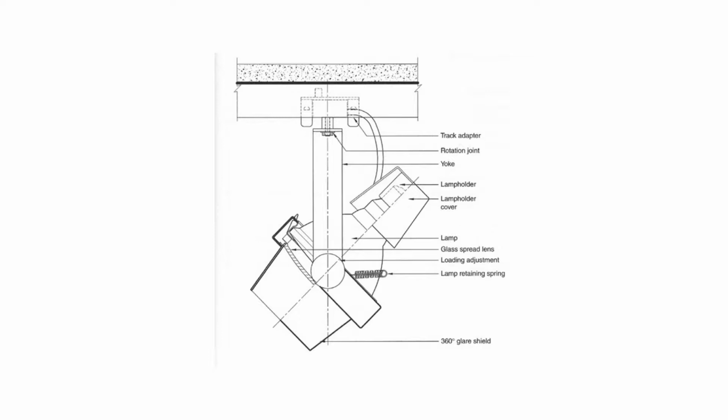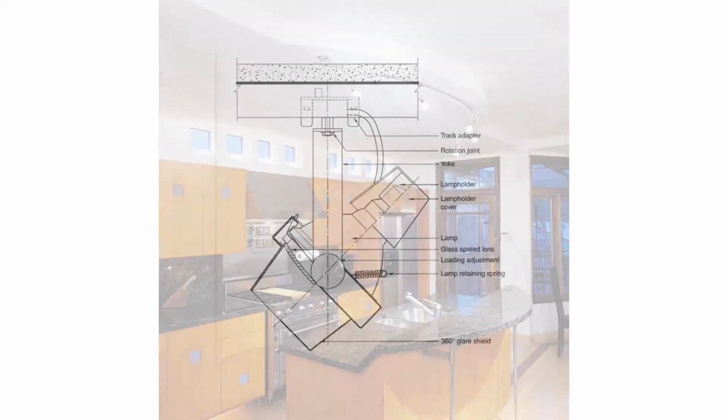It's called a gimbal fixture because it has a gimbal ring, which, if you know anything about photography, is a kind of multiple adjustable fixture. It can rotate both in the XY axis and in the Z axis, and you can put all sorts of different lamps in there. The ones we have in the Art Center are an old style screw-in lamp, but I think it actually might be a bipin lamp. They used to be MR lamps, which were great for lighting artwork. Now they've all been replaced by LED.